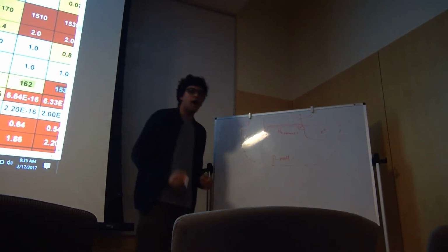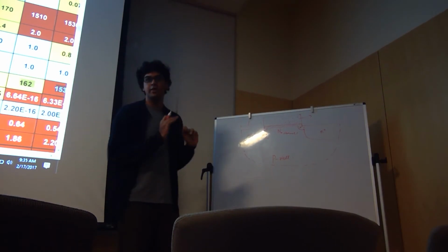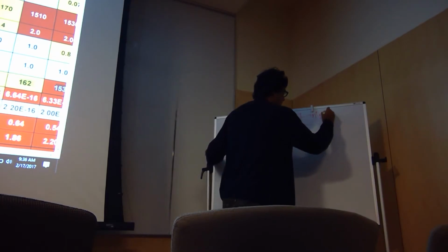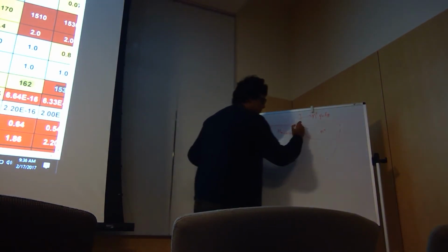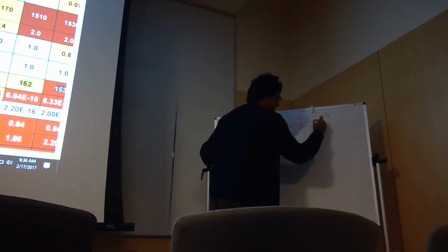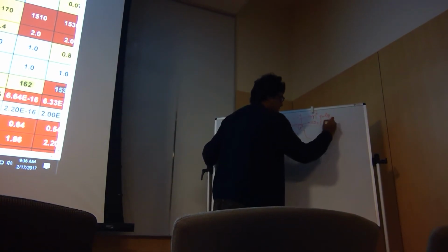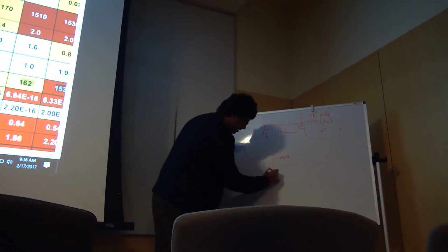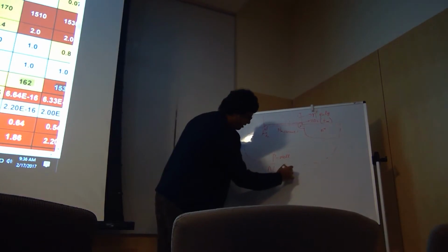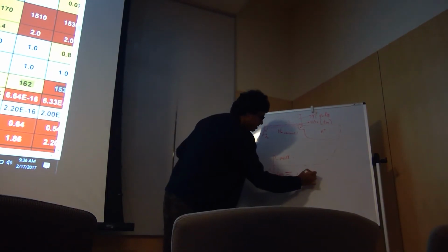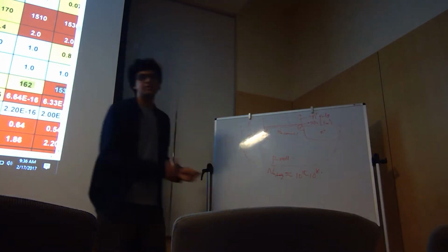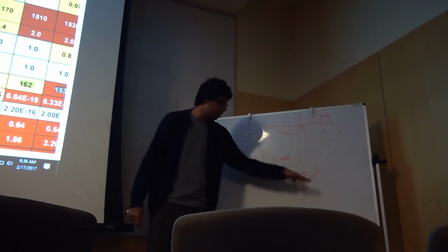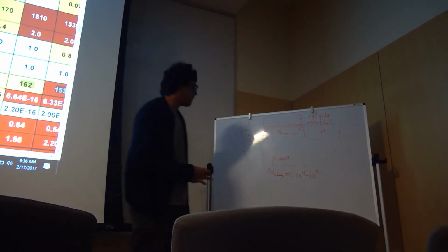For our purpose, we are going to assume the gate is poly, okay? So we are not going into metal and high K. So this is going to be N plus polysilicon. This is your oxide, which you're going to assume to be SiO2, and say this has a particular oxide thickness Dox. And assume your body doping. Body doping is typically on the order of 10 power 15 to 10 power 16. So when you choose your silicon wafer in Coventor, just choose this doping, okay? A ballpark number between 10 power 15 and 10 power 16.